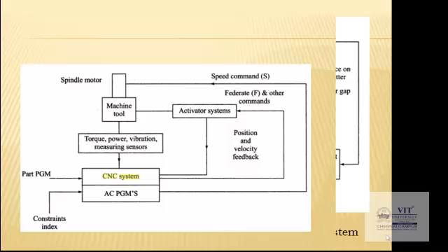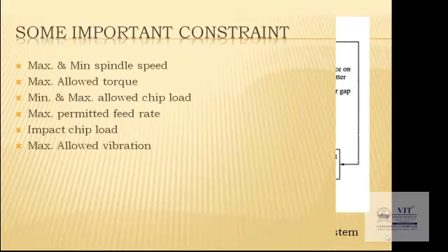It is sent back to the machine tool and actuator system. The actuator system is the feedback controller, so it obtains that value, modifies the program, and executes it in the drive. So this is an adaptive controlled system with the constraint value. The required workpiece is machined and the quality is obtained. So this is another system called adaptive control with constraint.